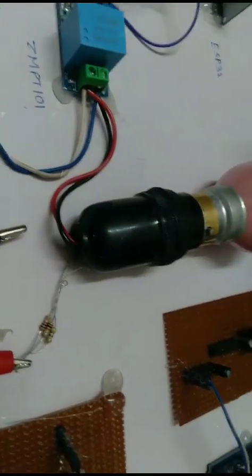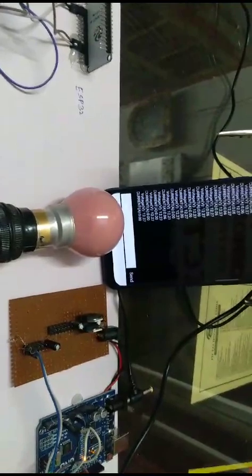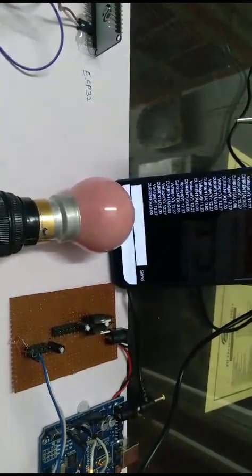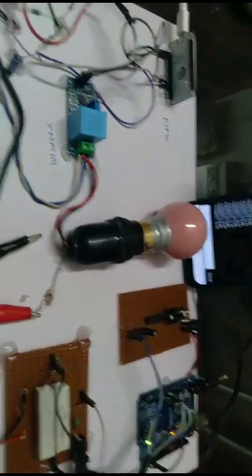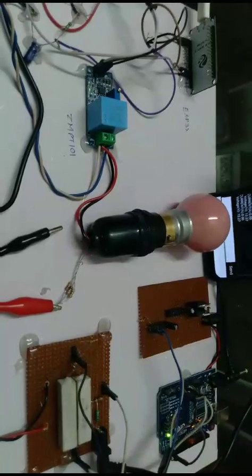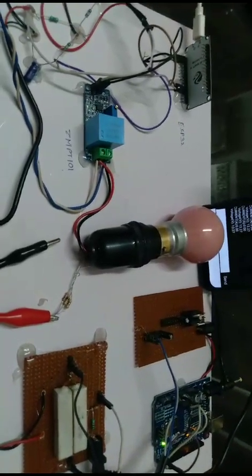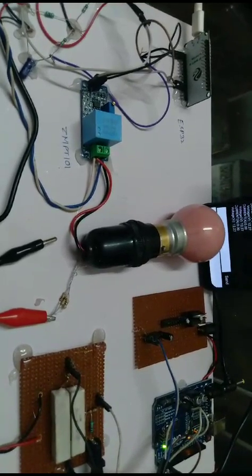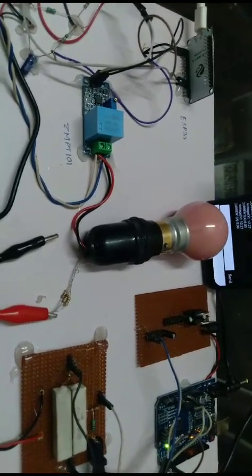When we reduce the resistance here, then the current can vary similarly in milliamperes, and the capacity to measure the voltage and current is 3 ampere and voltage up to 32 volt. So finally we built the AC and DC voltage and current measurement. You can say that it is an IoT controlled AC and DC voltage and current measurement circuit.